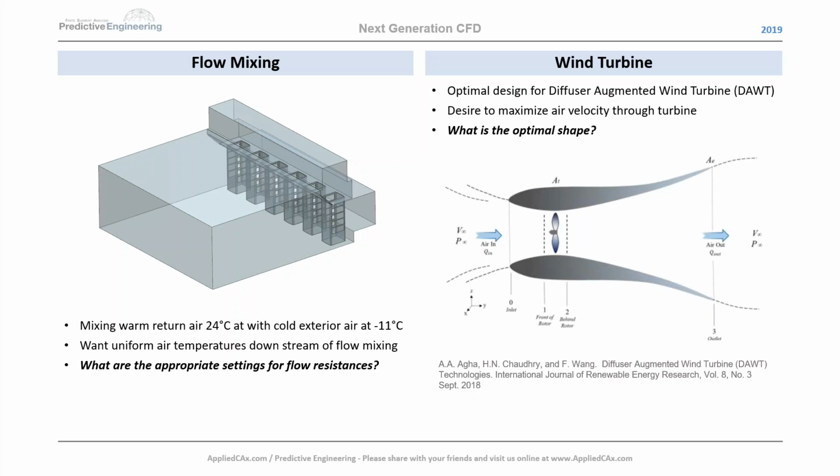And if these streams do build up, if you don't get mixing, they'll stay that way and they're actually going to the ventilator and you get hot and cold spots inside the system. So the mixing, usually you have to have very large spaces and you have these blades that are set up to turn it. So this was an advanced mixing design where you're shooting in the external air down through the baffles. Those are through the columns, and the return air from the hospital are just coming in through the wide spot. And you got different temperatures and different flow velocities.